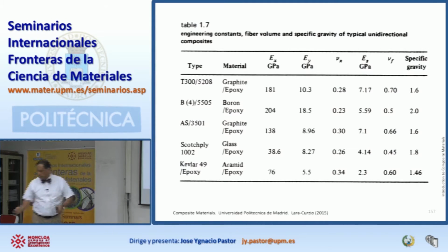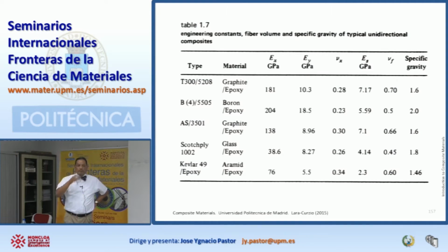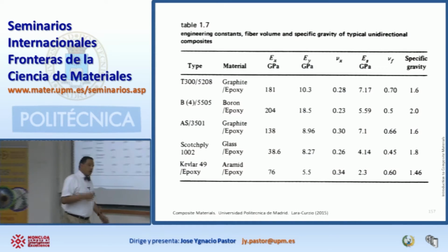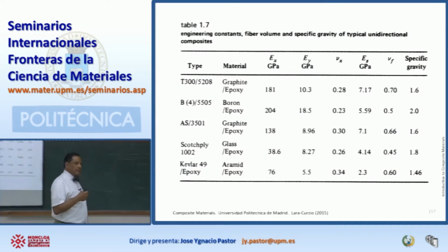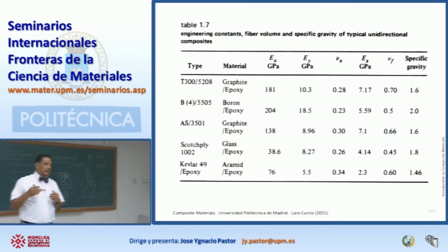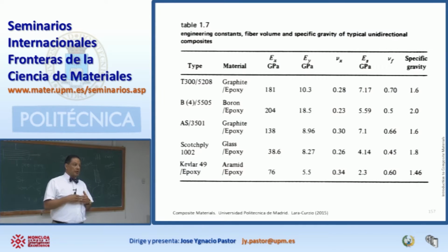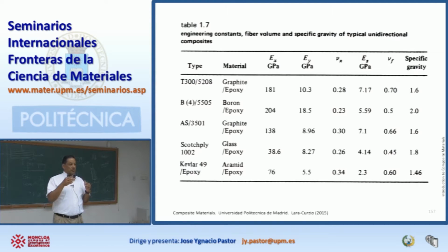Does the properties remain when we are dealing with ceramic composite where the interfaces are weak? That's a very good question. If you are in the elastic regime, where you have small deformations and the fibers do not debond from the matrix, the answer is yes. If you apply strains beyond the first matrix cracking stress, then everything breaks loose. So all these relationships apply only during the elastic regime where the interfaces are well bonded.